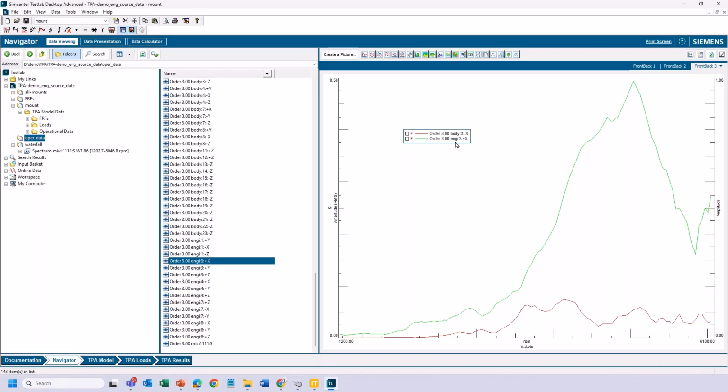Passive is body, active is engine. Yep, because the engine is doing a lot of moving, right? I guess we have visual confirmation that it's the active component because its vibration levels are a lot higher than the passive side. When we pass through this rubber mount, the high levels of vibration on the engine are reduced and you get a lot less vibration on the structure side.